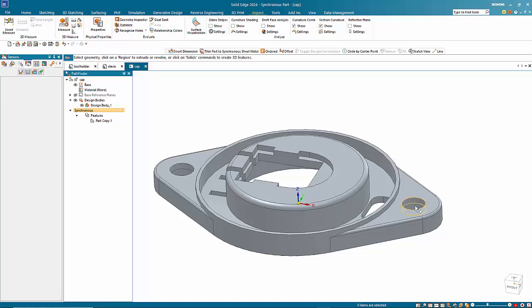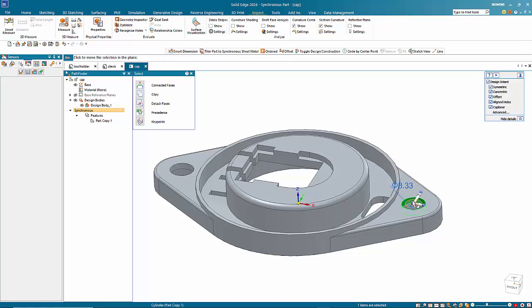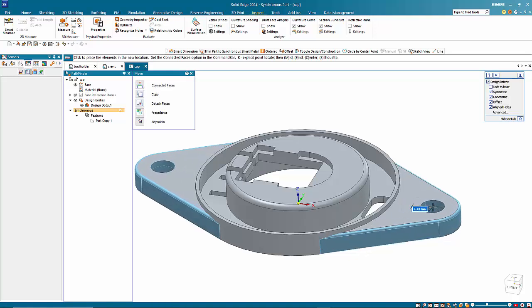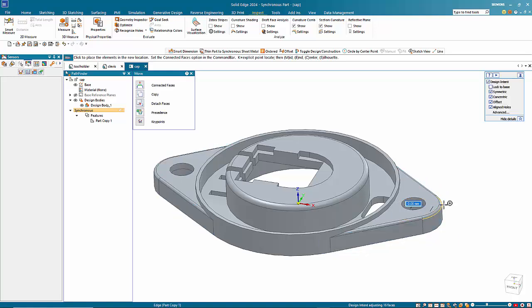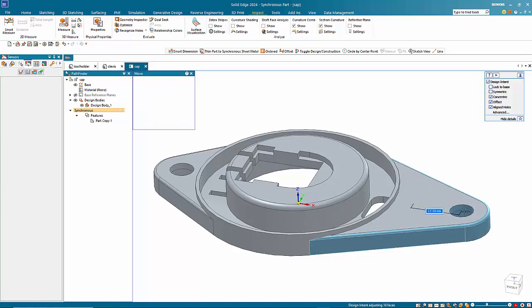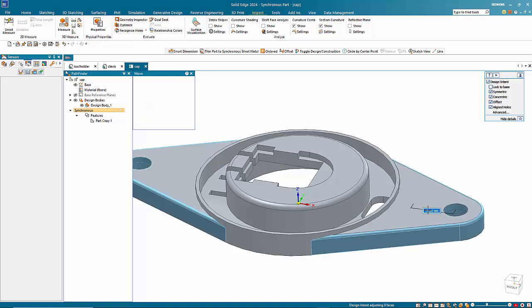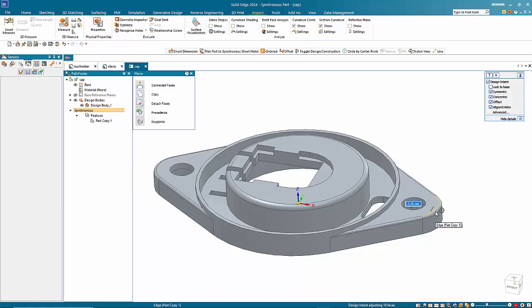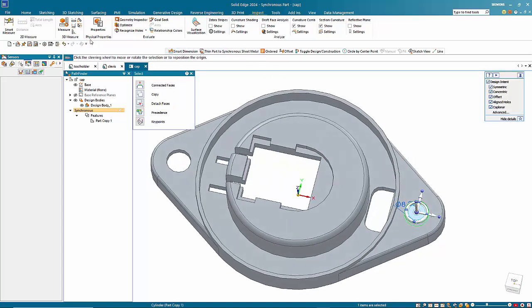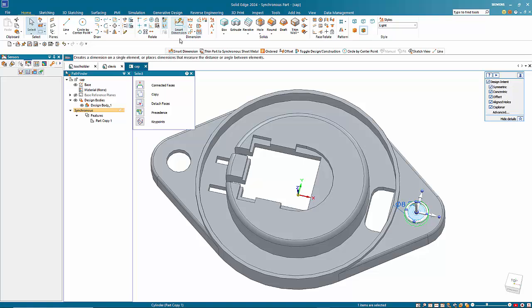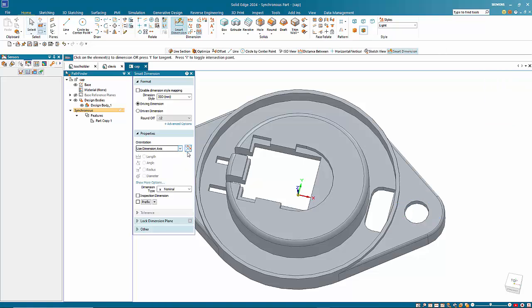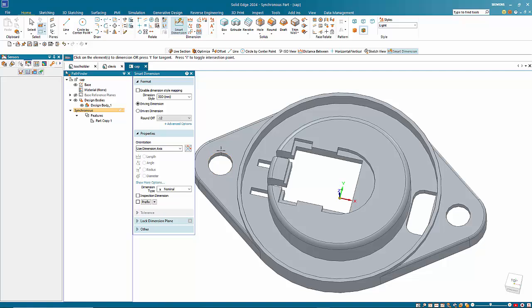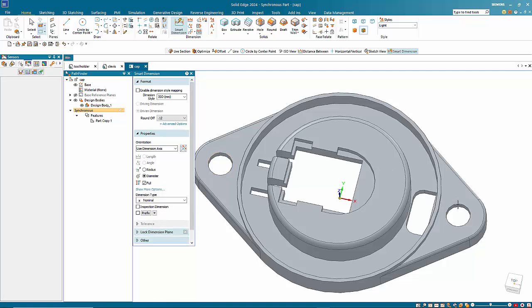We may want to change the width of this. If I click on the arrow in this direction, we've got symmetry on. I can turn that off if I want to have one side bigger than the other, but that is controllable just with the S key. I can turn that on or off. Also, we can add in a dimension, so I can dimension between the two items,